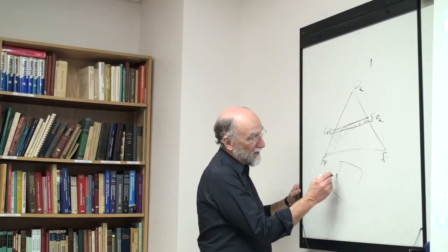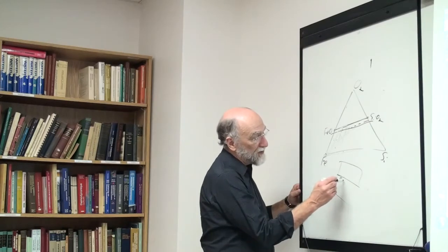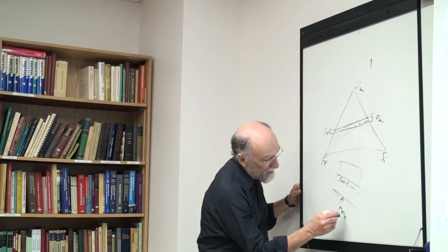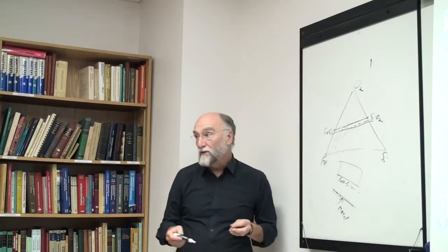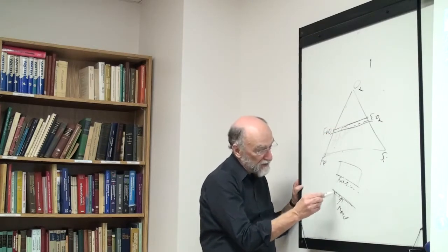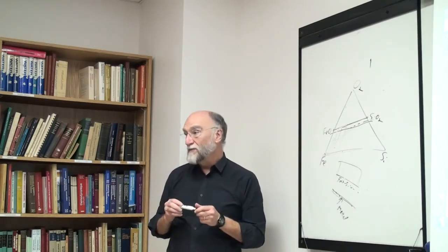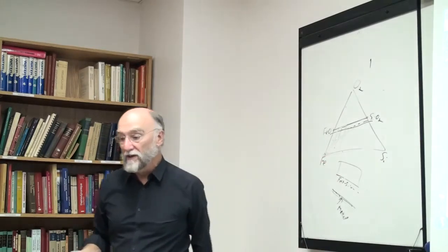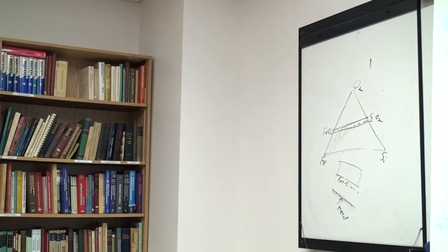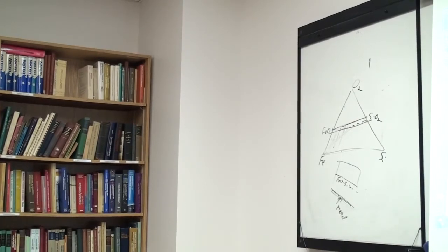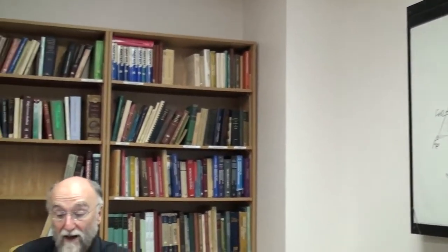You can imagine that you have here your oxide phases, your FeO silica, and down here you have a metal phase. The metal phase is a very small amount. So basically your composition is giving you the composition of this phase in equilibrium with a very small amount of metal, to assure equilibrium with the metallic phase. And that is the safest way to do these. So I define it as temperature, and the components are FeO, silica and iron.